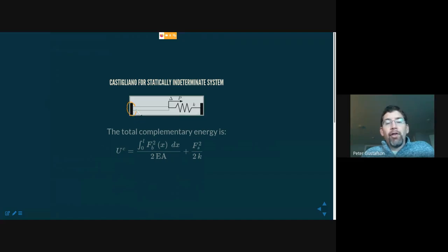So the displacement at this end will be 0 because it is fixed at that end. I would avoid calling it cantilever just because this is not a bending problem, although you probably would have communicated your intent just fine and it would have been understood, no problem. But it wasn't clear whether you might have been referring to this end, and the displacement at this point would not be zero, obviously, because we're applying the load there, and everything in the world is deformable at some level. You're going to get some deflection there.